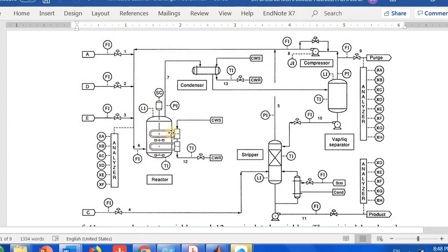And because it is at a certain temperature and pressure, you would expect that there is a drop of pressure because of the condensation, because of these long tubes, because of the separation. I mean, there's a lot of pressure drop here. You have vapor and liquid, and that vapor needs to be pressurized through a compressor, so then it goes back to the system here.